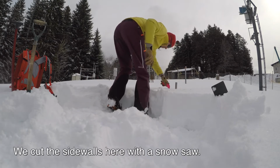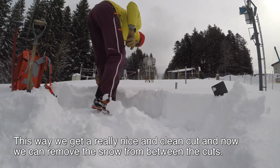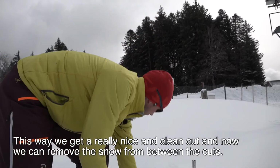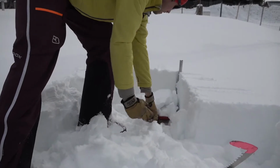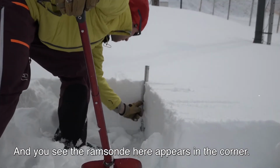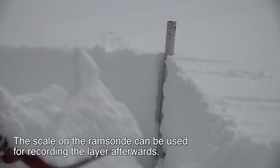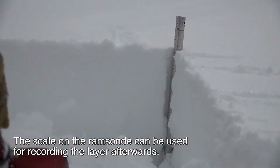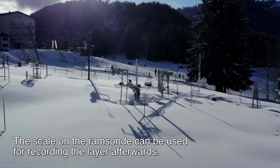So we cut the sidewalls here with a snow saw. This way we get a really nice and clean cut. And now we can remove the snow from between the cuts. And you see the Rammsonde here appears in the corner, and the scale on the Rammsonde can be used for recording the layers afterwards.